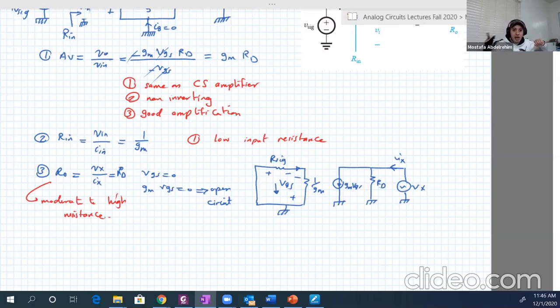So you need a load resistance equal to the equivalent resistance of the coaxial cable, so that there will be no reflections. So for such applications, we will need common gate amplifiers, or common base, which is the corresponding one in BJT transistors. Both have very low input resistance, but it's beneficial for such applications.